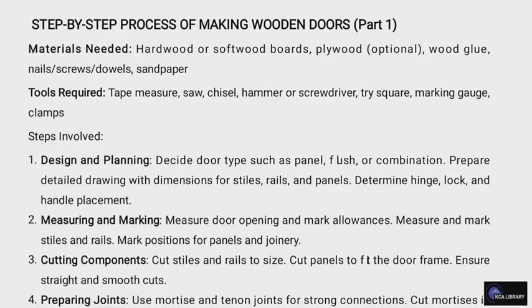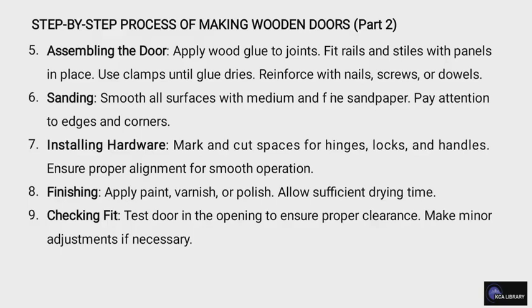The next is preparing the joints, using mortise and tenon joints for strong connection. This is very important. After that, you assemble the door and apply wood glue to the joints. Then you do the sanding, smoothing all surfaces with medium and fine sandpaper, and then you install the hardware, that is, mark and cut spaces for hinges, locks and handles, and ensure proper alignment for smooth operation.